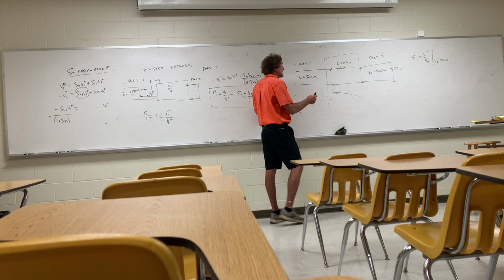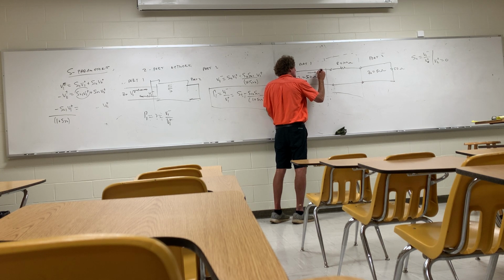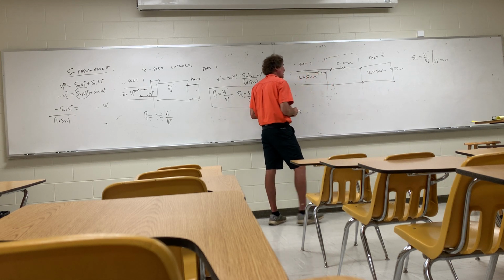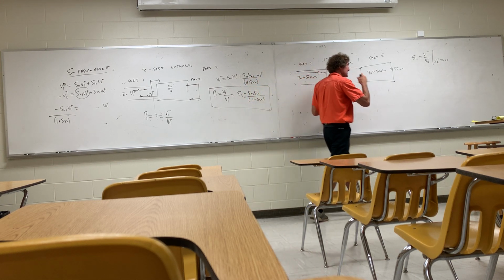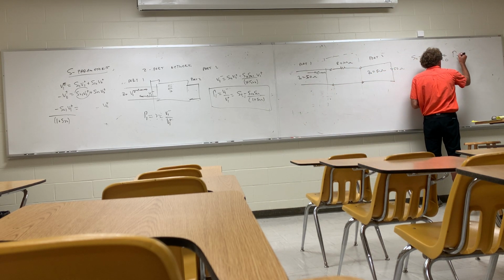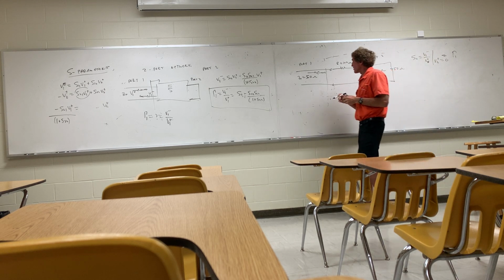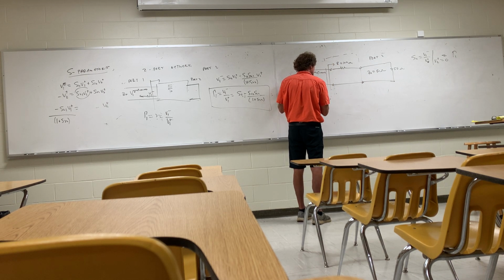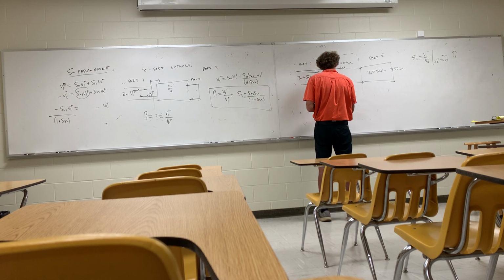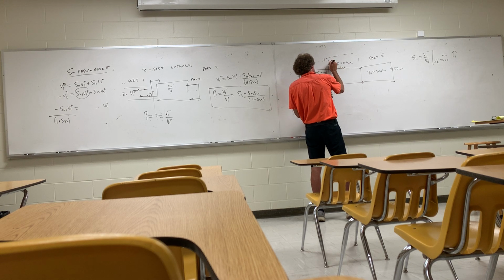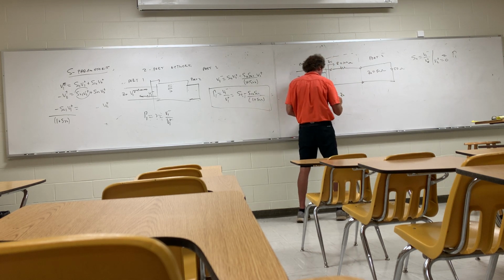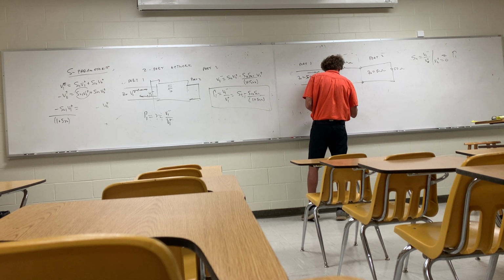So now I look at this, and I have my V1 plus mentally coming at this thing. And you know this from the past. Anytime you're talking about a reflection coefficient at this port, that's what this is. This is the reflection coefficient at that port, assuming that V2 plus is 0. What you're really talking about is the impedance you're looking at. When I look at this reflection coefficient, which is S11, the reflection coefficient of port 1, I'm looking at simply the Z in that I see there, minus Z0, the impedance I came from, over Z in plus Z0.